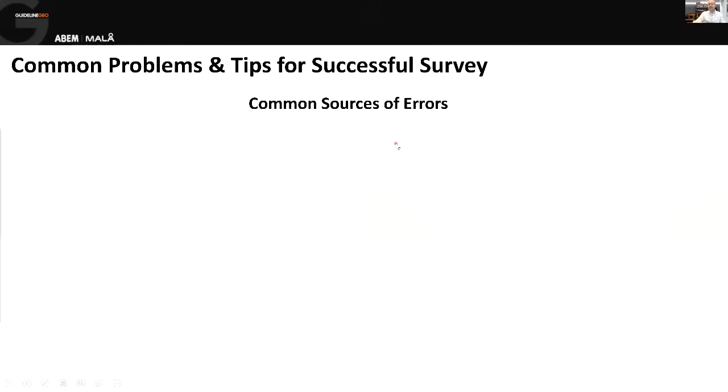So that's all while we're in the field. That's what we can do whilst we're collecting data. I had a look on our support system to look at why people have issues when they send us data that perhaps has high standard deviations or lots of negative values. And I can trace the source of the problems normally back to one of three things. And that is the position of the electrode and the material immediately surrounding those electrodes, the power supply, i.e. the battery, or the settings that have been used for the measurement.